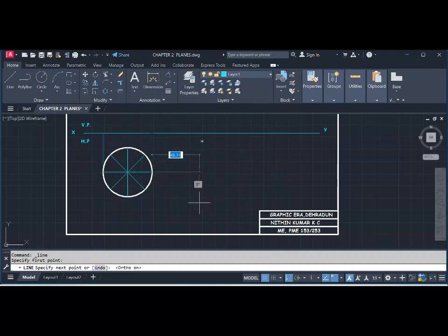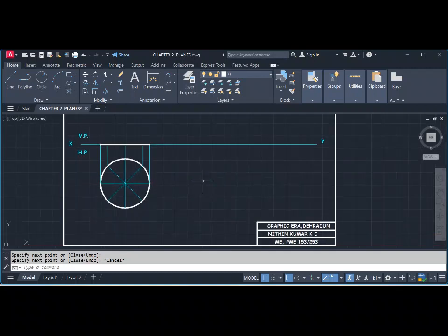Now when you see it in the front, you are able to see this line and only this line, but the lines which are inside are these lines. This way of dividing the circle to get the projection is called a generator. I am going to include this to make my work easy. Generally, for any curved surface where you want to make the projection, we use generators. Generators are nothing but dividing the curved surface into a number of equal parts. Then we proceed with the projections.